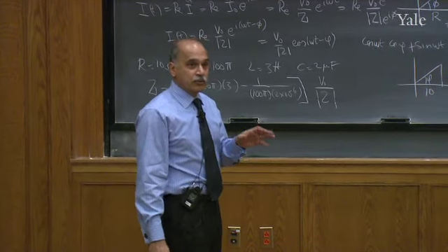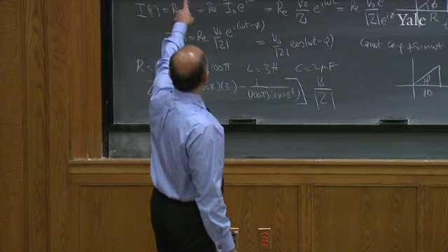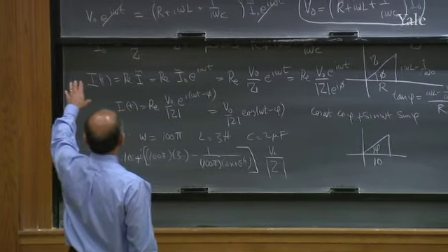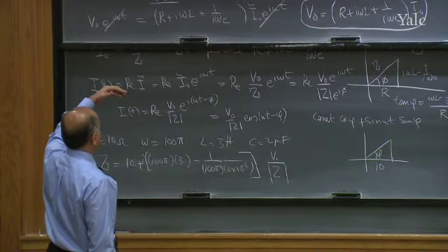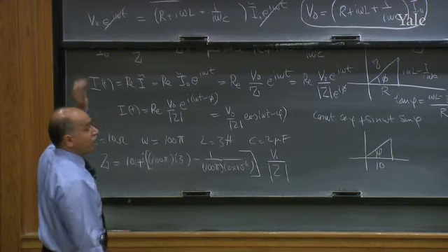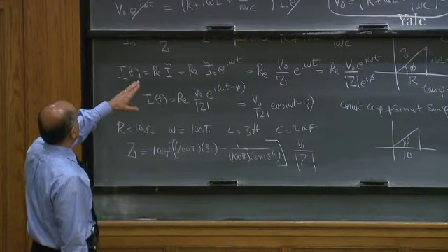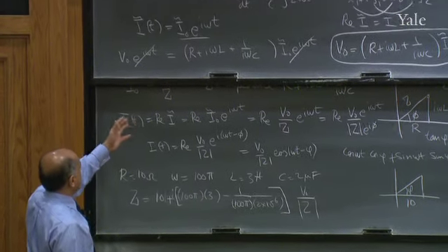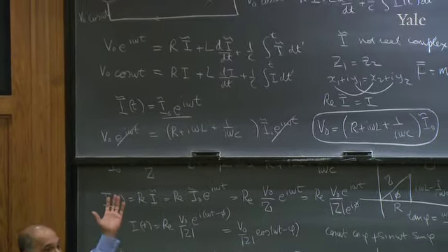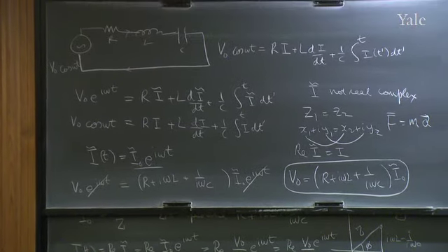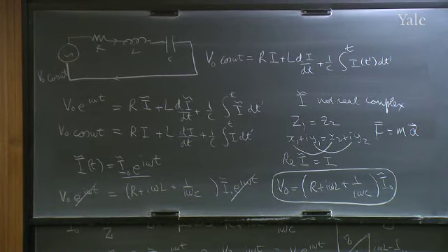If you don't see that, you should do that. Take that equation for any V of t, get an answer due to V1, call it I1, another due to V2, call it I2, and add them up. Left-hand side is clearly V1 plus V2. On the right-hand side, R times I1 plus R times I2 is R times I1 plus I2, and so on. So I1 plus I2 will satisfy the equation when the driving voltage is the sum of the two voltages.